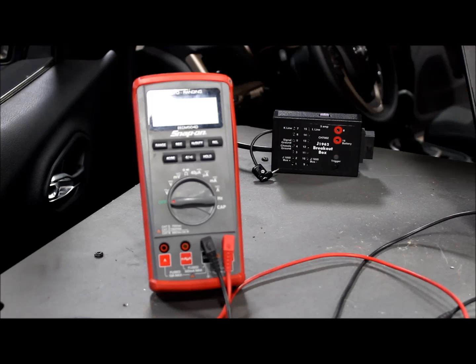The termination resistors are integral to the star connectors. So I showed you this on the bench. I talked about 120 ohms. Apparently these are 120 ohm resistors in parallel, and the total resistance you should measure is about 60. So let's see what we get.